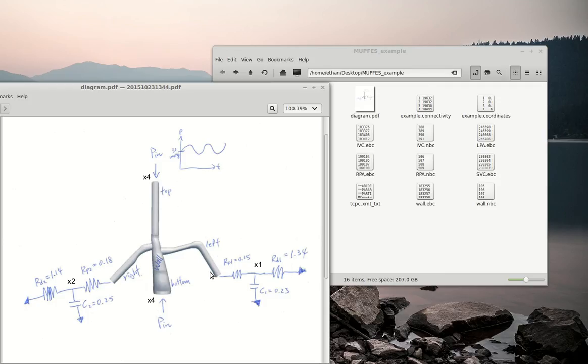And so in that case, you would need to manually provide pressure information to your 0D model in order to be able to run it standalone by itself. Basically the pressure and flow are reversed for a Dirichlet boundary condition. But I'll show you how to do that with a Neumann boundary condition, and you can apply the same principles if you have a Dirichlet boundary condition.